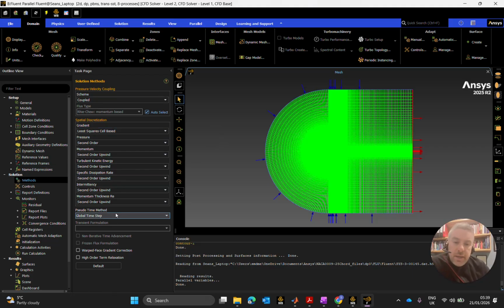Time stepping, yeah, we can change the time stepping, but we have 29 meters per second. We're just going to assume after initialization it's going to have 29 meters per second filtered out to some degree from an upwind scheme down. For upwind going back down, that's what upwind means. And it is steady. We have it in a steady state, so I wouldn't change that so much. It's fine. So there's nothing really else to change in here with respect to the methods that we're using, or anything to do with our pressure velocity or spatial discretization schemes. So that's what I propose we run with.